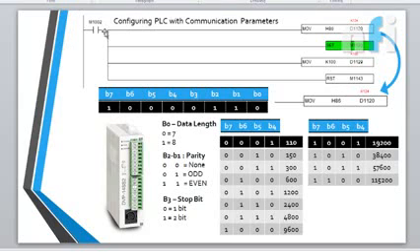Okay, so with this single pulse, what it is doing is moving H86 into D1120. Now what is that part? Let's discuss this command. I'm just breaking the parts. MOV H86 D1120. First of all, H is for a hexadecimal value, and 86 is the hexadecimal value. If I break this value H86, it will come like this: 6 is 0110, 8 is 1000. That's how you convert hexadecimal into binary, right? The first 4 bits represent the 6 and the next 4 bits represent the 8.